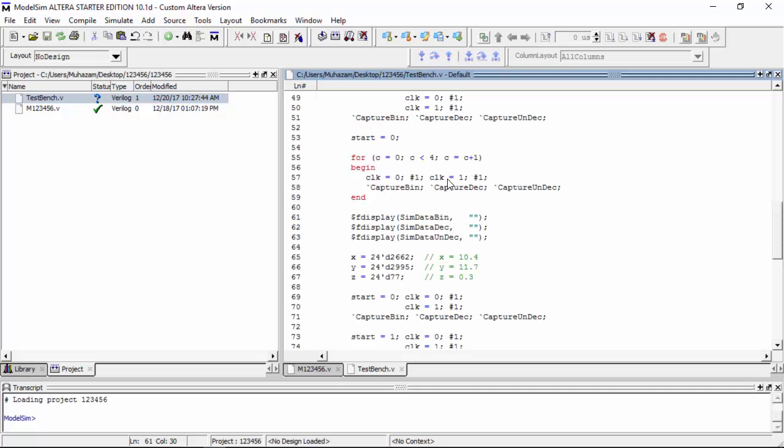For this assignment, you have to do 3 sets of data that you expect to be correct and 3 sets of data that you expect to be wrong. How to get calculation to be wrong is one way to give large value so that you have overflow somewhere in your calculation. That will definitely give you a wrong result. And another one, since in this calculation we don't consider sign, meaning anywhere the calculation result in negative value, it will also give wrong result. So let us save this and see the simulation again.